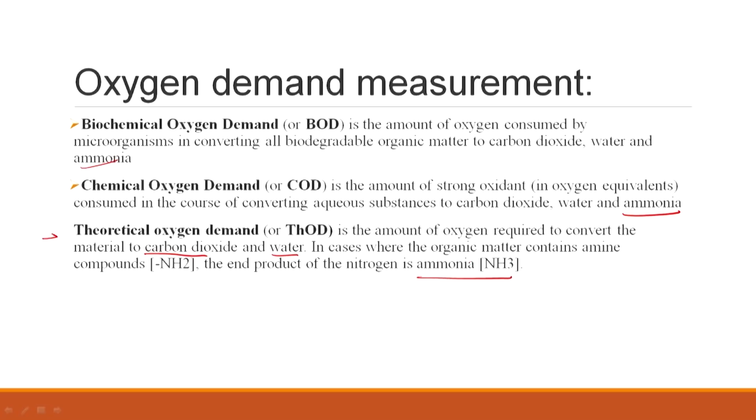But typically we rarely look at this. We measure BOD and COD because we want to know whether the bacteria can degrade your waste, or if it is remarkably non-biodegradable and will persist in nature. Let us say you have very low BOD and high COD, what does that mean? That means the industry is discharging waste into your water body that is not going to be degraded by nature or by microbes, and you will end up feeling the effects of this pollutant, and that is the case in a lot of our surface water bodies.